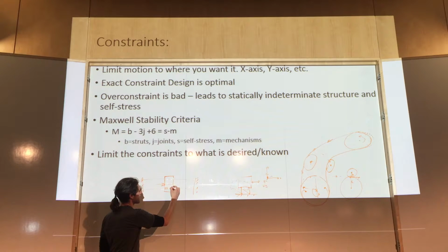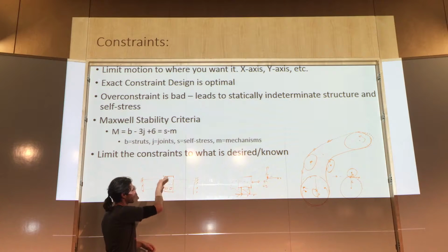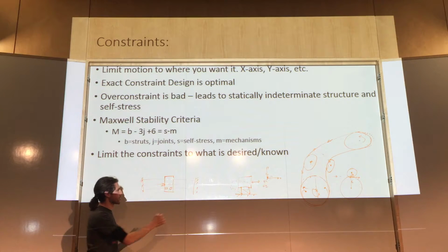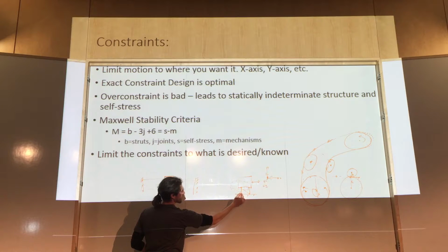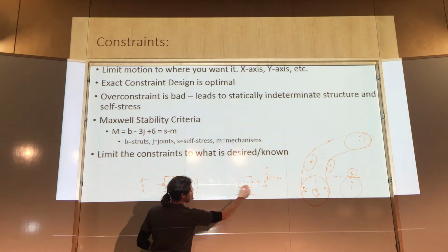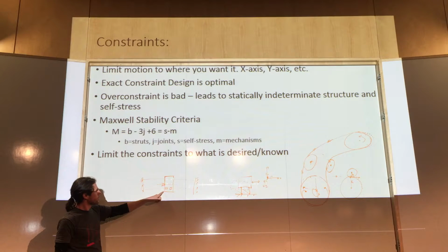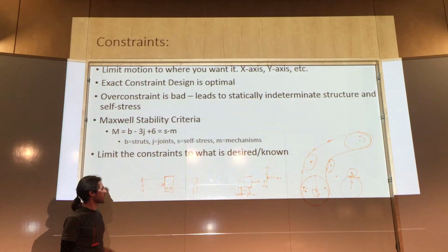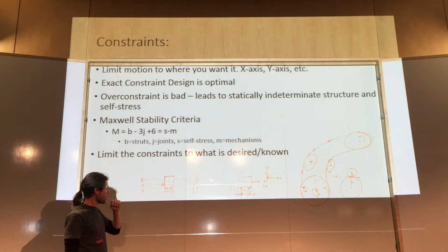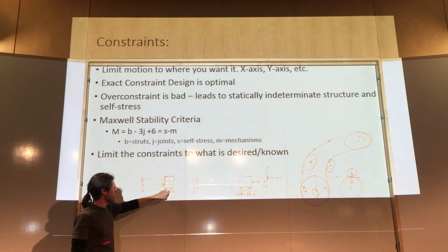And so you end up realizing, well, I want to put another bearing in there to prevent it from flopping around. And that essentially gives you these two constraints here that allow you to translate still. So you say, okay, I've got this guy constrained. That's cool, but they're pretty close together.